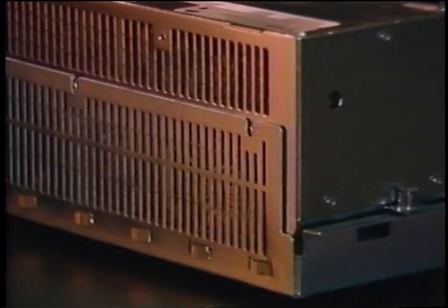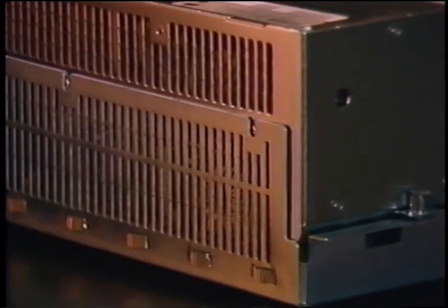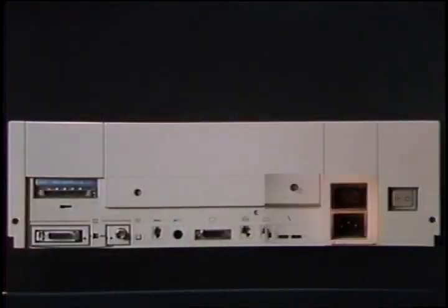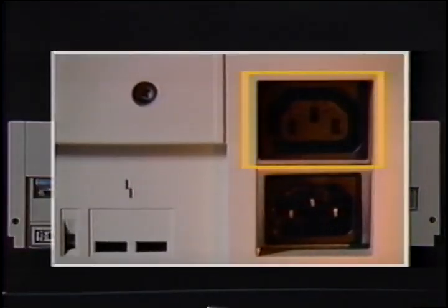Both VAXStation power supplies feature auto voltage select of 120 or 240 volts and are protected with 2 metal oxide varistors from undervoltages, AC surges, and transients. A switched AC output is available exclusively to power the workstation monitor. 8 diagnostic LEDs display troubleshooting information when a monitor is not functioning.